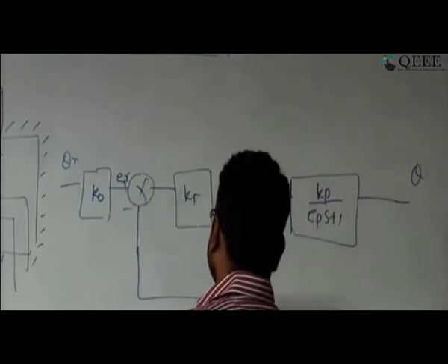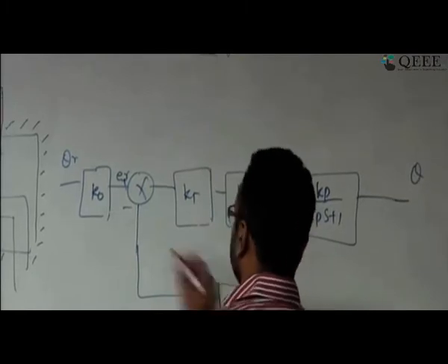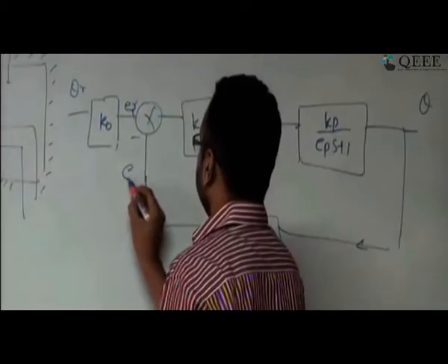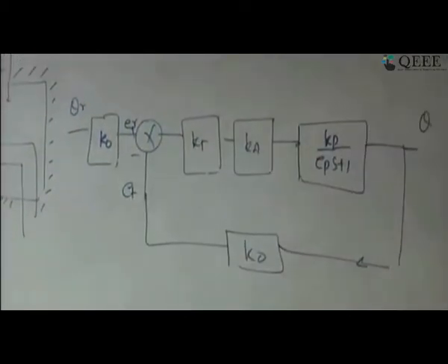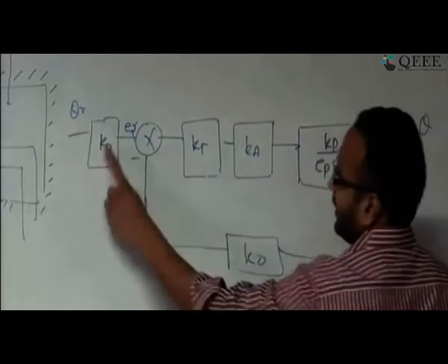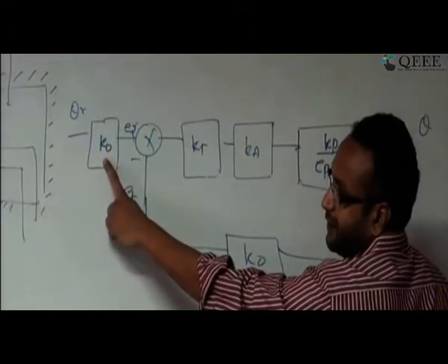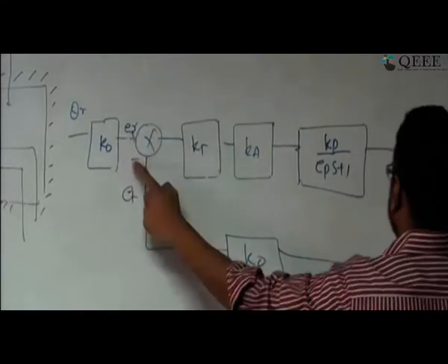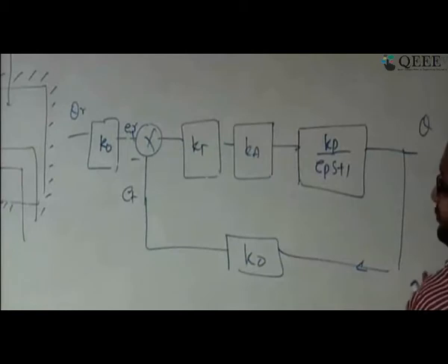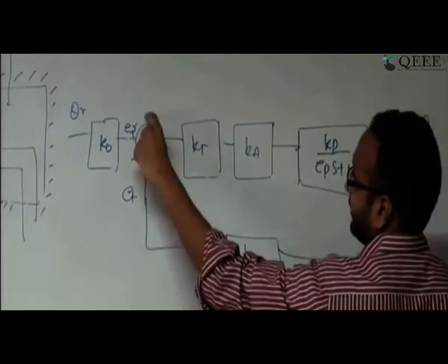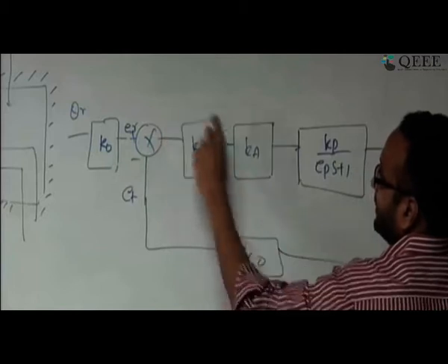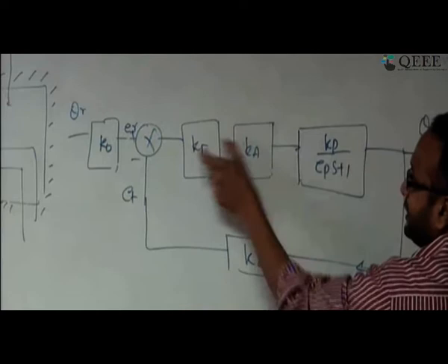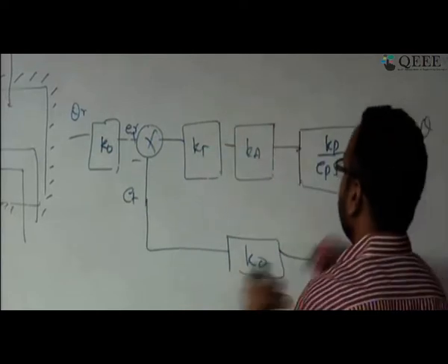And in the feedback path, I again have the same thermostat, which will measure the temperature from outside and change it to an ET. So this is very clear, as we just talked about. This is the reference signal. I have used an element, in this case the thermostat, to convert it to a voltage. Then from the output, I have got the actual temperature and converted it to a voltage. Then I have taken a subtraction. When the subtraction comes, I have an amplifier, followed by a transducer, and then the valve position. That valve position constant I can write as Kx.